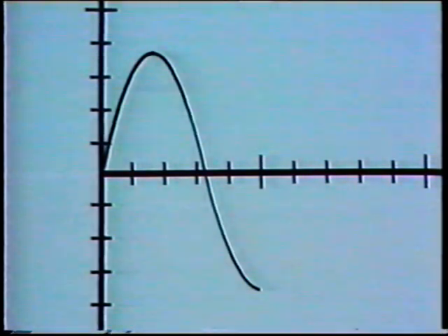Well, most AC circuits are rated according to the effective voltage, and that's less than the peak value. But when you're installing a conductor, you've got to be sure its insulation is rated to withstand the peak voltage. It's easy enough to be sure. You multiply the effective AC voltage by 1.414. This gives you the peak value of the AC voltage, and that's what you insulate for.